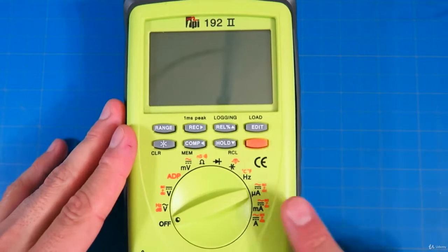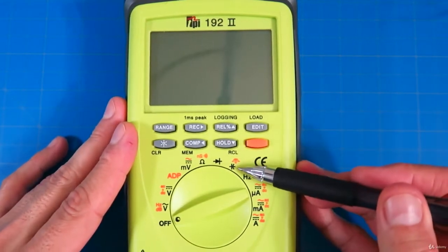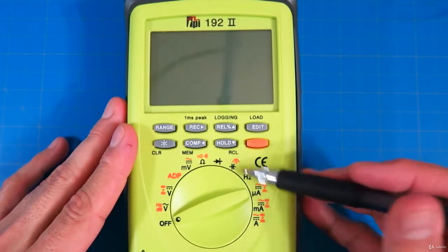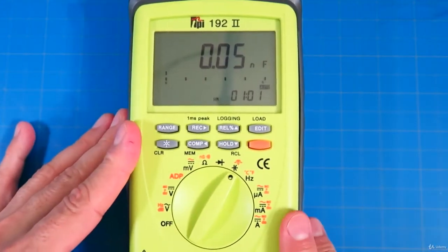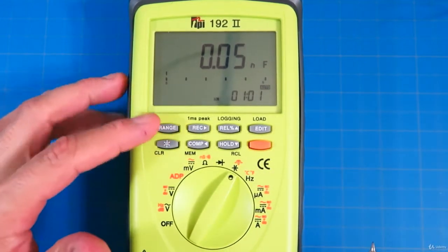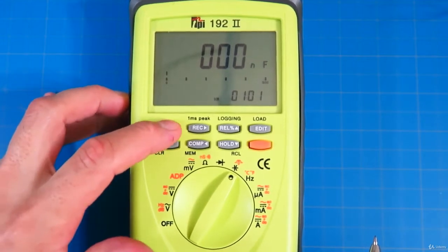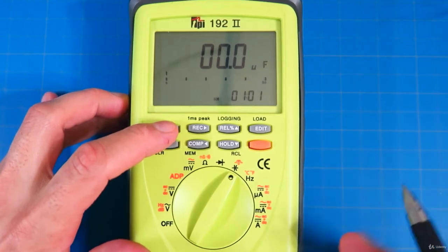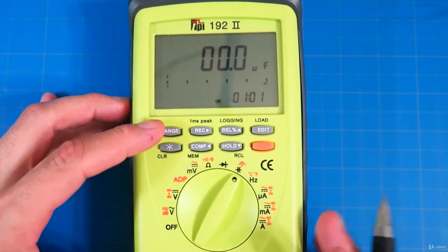All right, so let's turn this on, and if we look around at this dial, right here is the capacitance measurement. All we need to do is put it on that right there. So turn it on. All right, our meter is on, and see it's measuring now in nanofarads. And on meters, and we're going to go over this, we have a range button here. If I press this range button, it's going to start changing. So we're kind of giving it an idea where we think this thing is. So microfarads, tens of microfarads, right? I think this thing is probably a microfarad or so. So let's put it on that range right there.